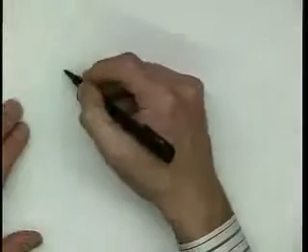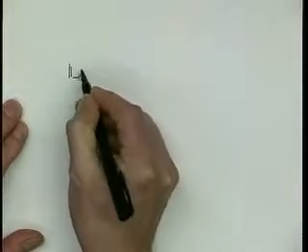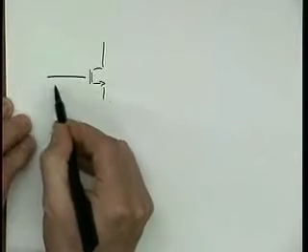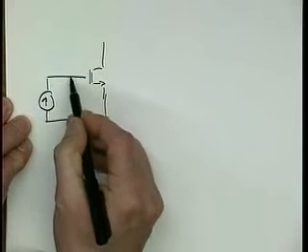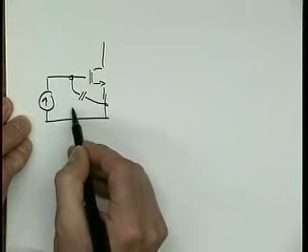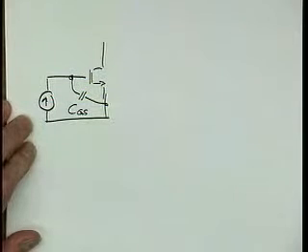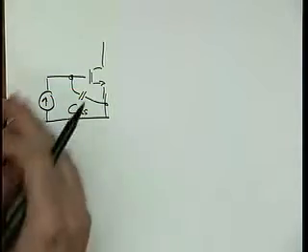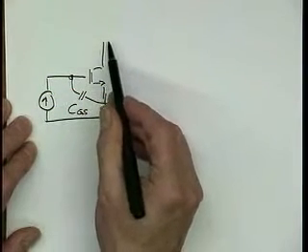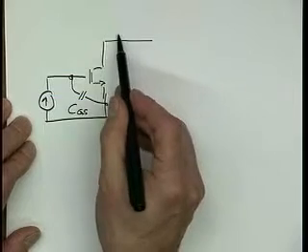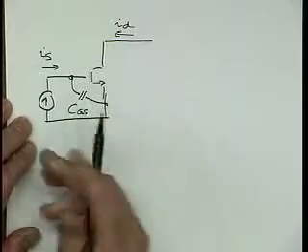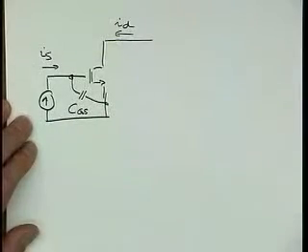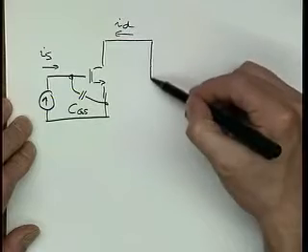What is it really? Well, if we have a MOSFET, and we are driving it with a current source like this, then of course that's the CGS, right, that this current is going to flow into. I'm not proposing that the MOSFET is going to have a leaky gate suddenly. Okay, I'm not interested in that effect, fortunately, yet. Right? And then of course it's going to produce a current ID at its output. So there is going to be a current I source that flows into this thing as a function of frequency, and there is going to be a current ID that flows into the drain, right?